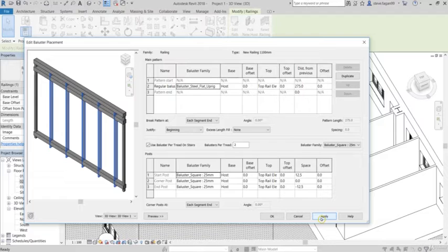If I press apply, this column here is the base. It's set to host. If I hit the little arrow, I've got a few options. I can go to the top rail, which is the one that we created just now, the bottom rail, which we just created, or the top rail element, which is that section there. For the base, I want it to start from the bottom rail. Press apply, and you'll see it will jump up to the bottom rail.